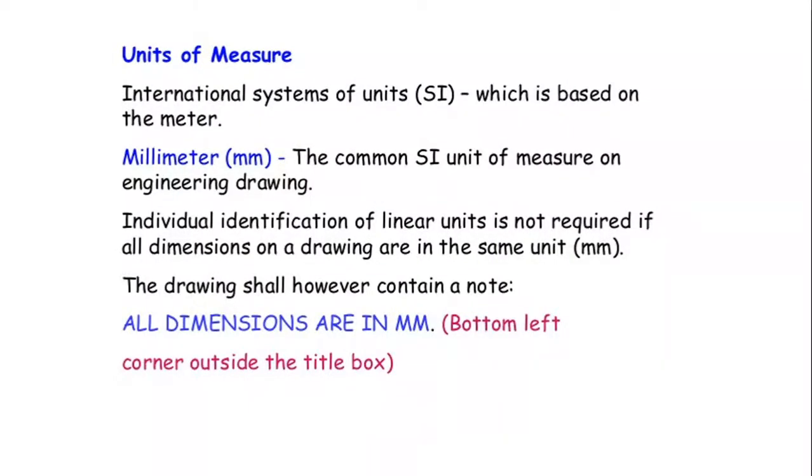For angles, you use degrees. For linear dimensions, you use millimeters only. The drawing sheet, however, should contain a note that all dimensions are in mm, at the bottom left corner outside of the title box. You use this in engineering graphics also, as per this standard.